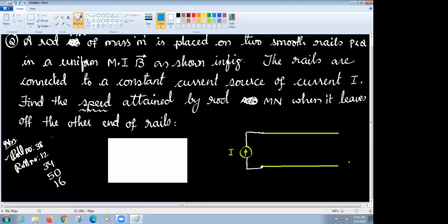You have Ohm's law. Whenever it is Ohm's law, we always say V is equal to Ri. And 1 by C integral i dt is also an Ohm's law. So I have various forms of Ohm's law, some nine ways of representing it. But in field theory, Ohm's law is J is equal to sigma E. From this only, all the stuff has been derived.